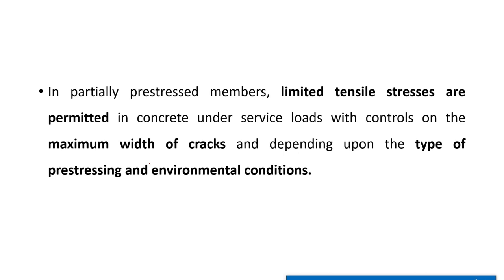Okay. And in type 2 members, which are also called limited prestressed members, some amount of tensile stress is allowed, but that is below the flexural capacity of the concrete. That will not cause any cracking. Some small amount of tensile stress is allowed.